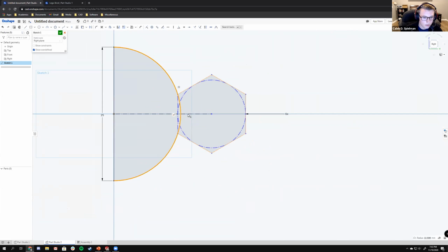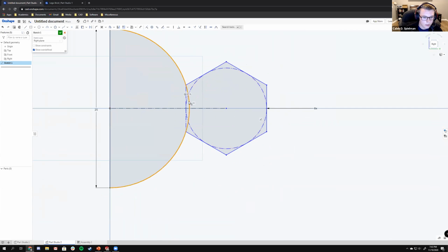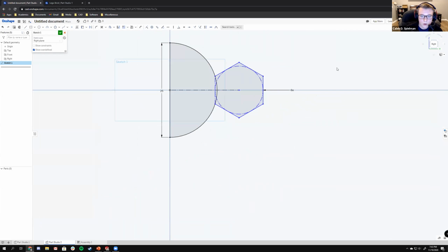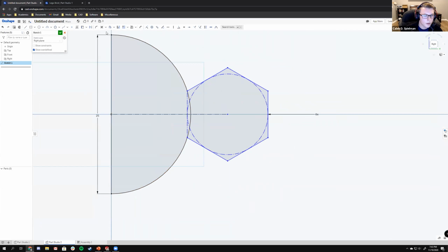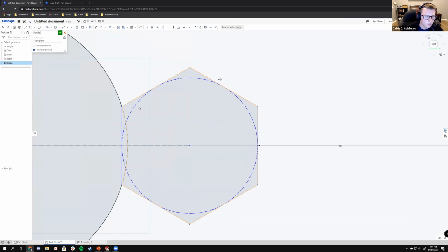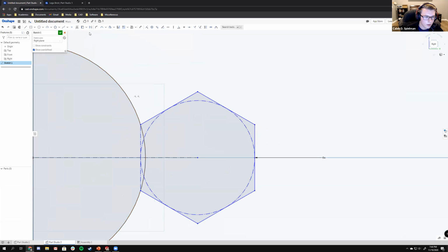How do I separate this line, you may ask? I can't delete it, that deletes the whole thing. Well, if you watch this, up here at the top, this little scissor thing, if you click the drop down, there are several options. Everything comes with directions, by the way, if you hover over it. We're going to choose split. So here, drop down menu, split. I'm just going to select this curve and click any point. Where'd it go?